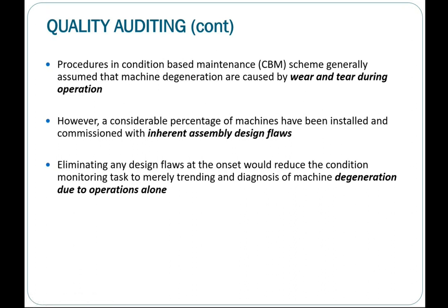okay, for example, imbalance and misalignments that were due to the wear and tear of your machine components, your couplings, your bearings, your so-called impellers or whatever is rotating, for example running 24/7 non-stop, then probably over time, if you have caused wear and tear to these machinery components, it will create a very high force on that particular machine, giving high vibrations.